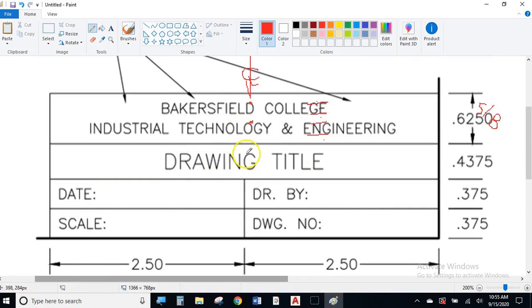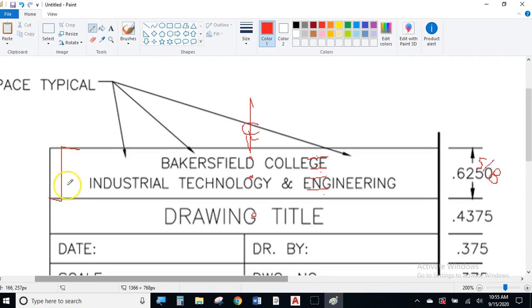In the middle box, the text is obviously bigger, so the instructions will tell you the size. The text is justified middle center, so the very middle and center point of the text will always be in the middle of the box. Okay, so if I have a big title, it will stretch out equally on both sides. If I have a short title, well, it'll be shorter, but it will still be equally split between the two sides. Okay, now to find the middle center of the box, my suggestion is this: draw a line from corner to corner.